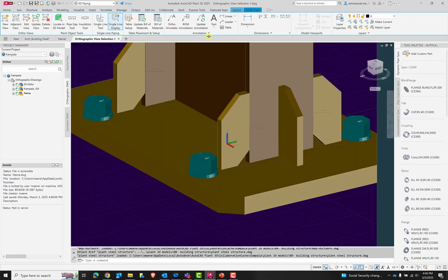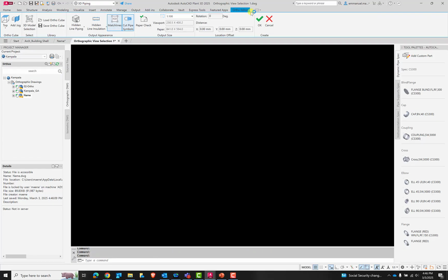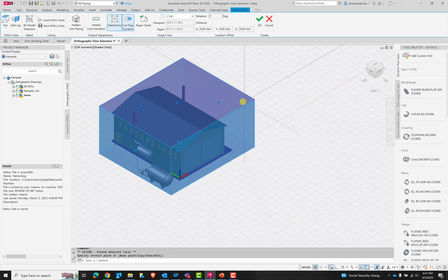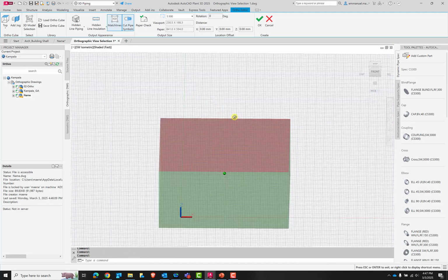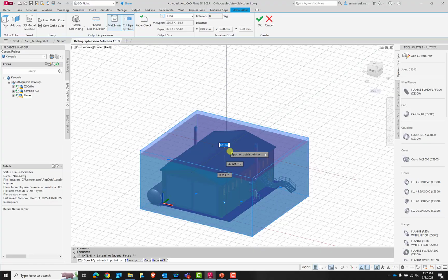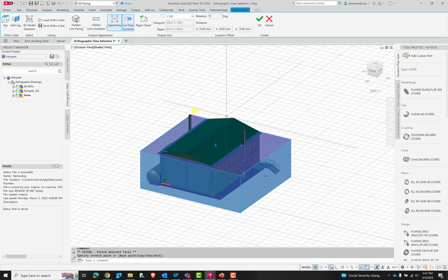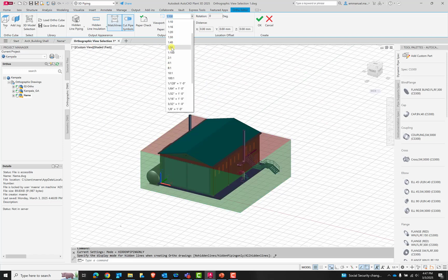it allows me to now do some bit of settings. For example, this view I can now reduce, change the scale, and jog the drawing if I need to. I'll make sure that my hidden line piping setting is on, and then set my drawing scale to be 150.